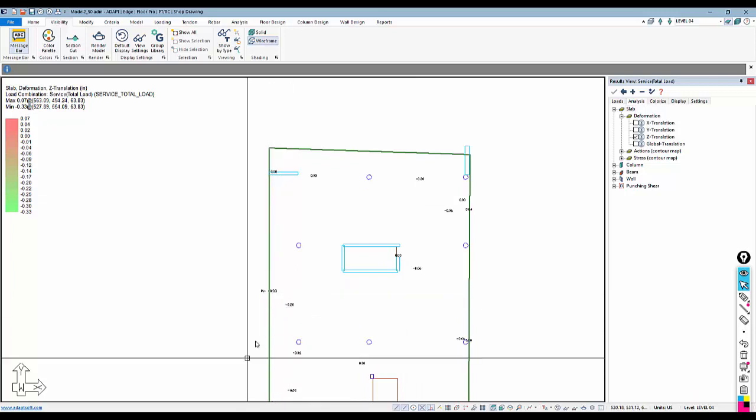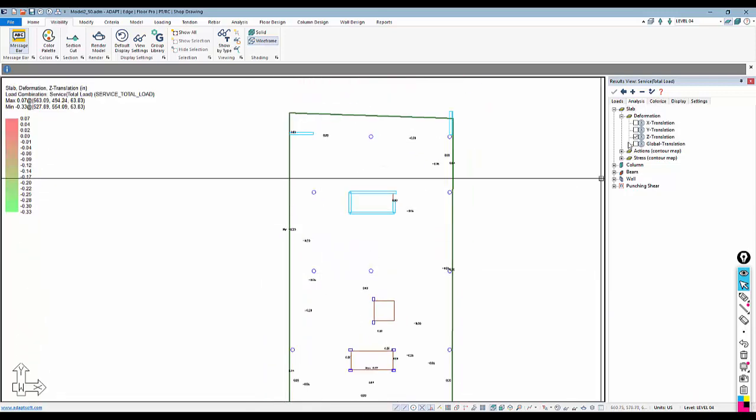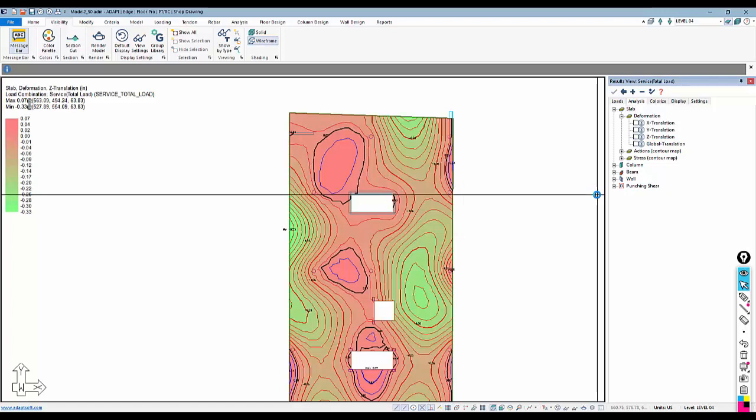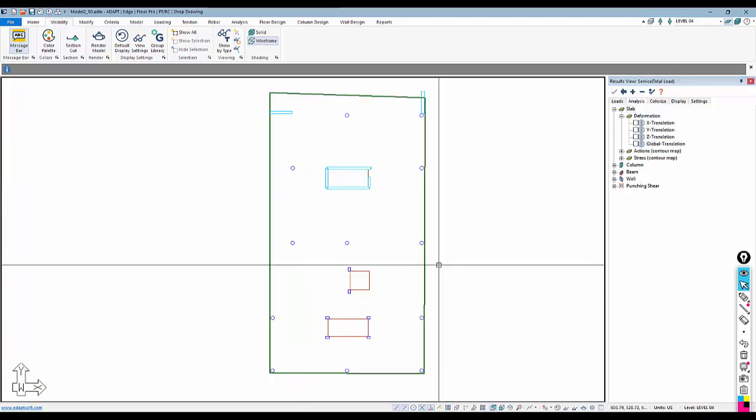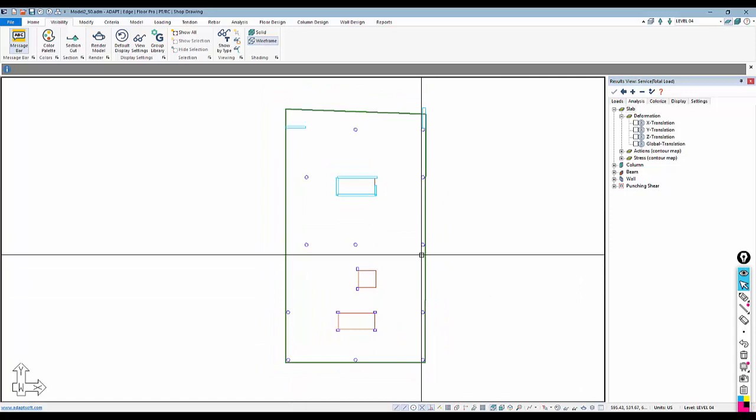Again, max deflection is about 1/3 of an inch here on that cantilever. Now, as we adjust tendons in order to meet some of the requirements for the post-tensioning in the slab, that deflection would change. So once we get downstream into a design, the user would typically then check crack deflections and long-term deflections in the program.